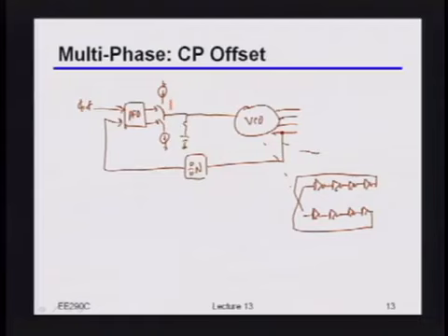Yeah, right? Remember we said that if we have mismatch in the charge pump currents, that, for example, let's say your I up nominally looked like that. But let's say your I down, for the same nominal width, was larger. And we said that the loop would actually compensate for that and make it so that the net charge in both of those was the same, right? And the only way to do that is, of course, to make the up wider than the down. And if the up is wider than the down, that implies there's a phase offset.